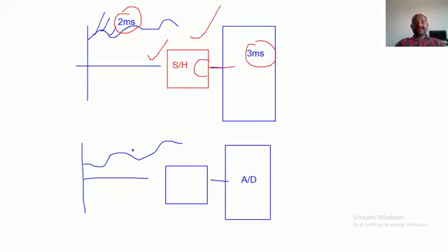Meaning, if the input signal is varying very fast and the analog to digital converter is also working at high speed, in order to avoid losing a fractional variation in the input signal, they are using the sample and hold circuit in the analog to digital converter.